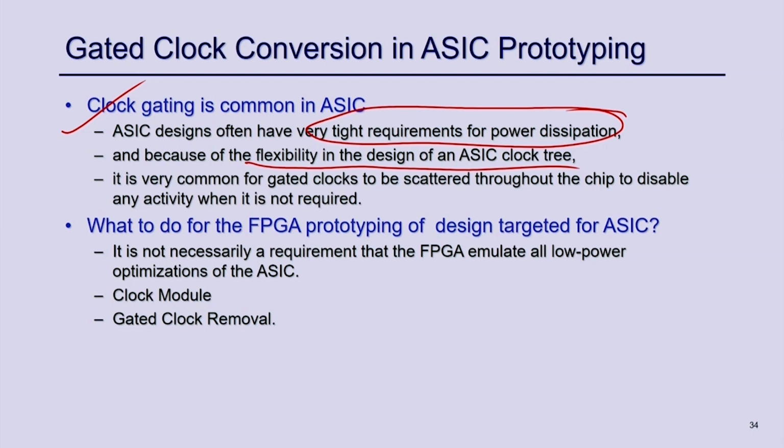But now the question is, when you are doing ASIC prototyping, what is ASIC prototyping? You have a circuit, and it is a very big circuit. Just think about a processor. Before fabrication, you try to simulate your actual circuit and see whether it is working or not, right. That is a very common practice done by any chip provider like Intel or other companies, which run the whole processor on FPGA boards. Multiple FPGA boards, maybe 10, 15, 16, 80, are stacked together, and the whole processor, which may be a million lines of Verilog code, is synthesized into the FPGA boards, right. And then that becomes your processor.